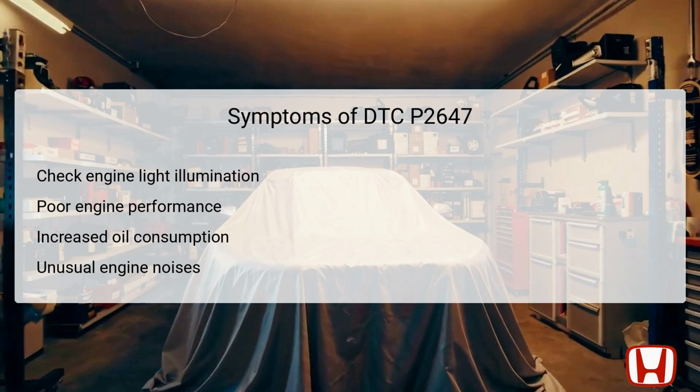Furthermore, poor engine performance may manifest as sluggish acceleration or an uneven idle, making it evident that something isn't right. Additionally, drivers may observe an increase in oil consumption coupled with unusual engine noises, such as ticking or knocking sounds, indicative of insufficient oil pressure. It's crucial to address these symptoms promptly to prevent further damage to the engine.